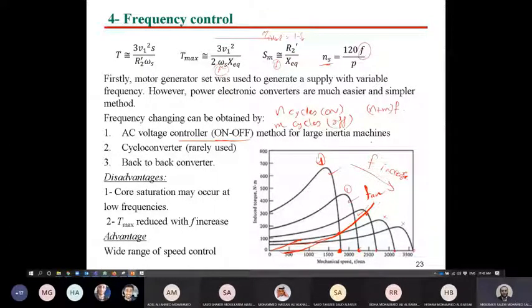Okay. Another device, guys, called Cyclo Converter, but it's not used anymore. These Cyclo Converters started in industry, as I remember, or the first famous project or well-known project was at 1940 something. So it's a very old technique or very old topology, Cyclo Converter. But the used topology now is the back-to-back converter. This is the most one used for frequency control in industry.